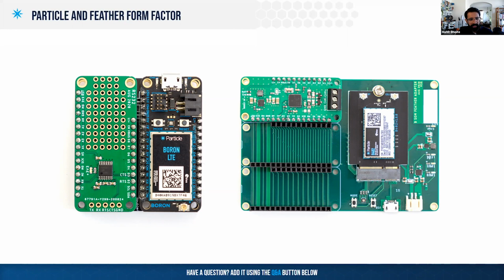They're all open source. So what I like to do on the Studios team is quickly evaluate a particular part number. For example, on the left, you see the RS-232 level converter. I was able to quickly evaluate that it works and that my footprints are right. So even without making the whole board, I can quickly evaluate these parts individually.